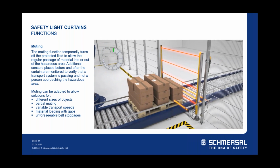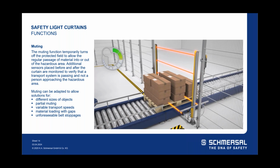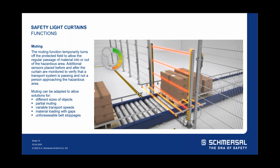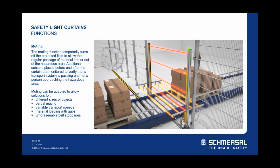So you can see how it's hitting sensor 1, sensor 2, then the light curtains, then sensor 1, sensor 2 on the way out. Everything is the same on the way in as it is on the way out. After the temporary suspension, it reestablishes the light curtain. So if someone tried to walk through there, they wouldn't be able to break the beams in that order, in that sequence, and therefore the light curtain would shut off and not allow that hazardous motion in behind to still be moving.